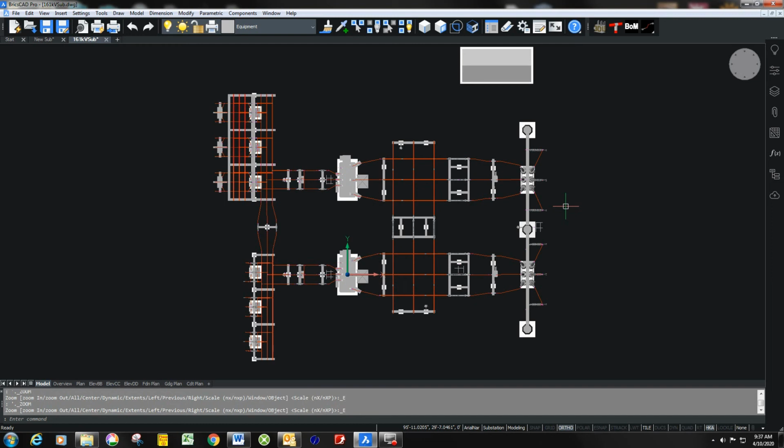Okay, let's have a quick review of AutoCAD's 3D development. In AutoCAD version 2.6, released in 1987, 3D Level 2 introduced 3D lines, faces, and plotting. This allowed for the creation of realistic 3D drawings. AutoCAD 2007 added the SectionPlane command that provided the ability to define sections, also called elevations. And finally, with AutoCAD 2010, the essential SectionPlaneToBlock command was introduced. This added the ability to create a flat projection of the section. It is these last two commands, along with the concept of paperspace, that we are going to explore here.